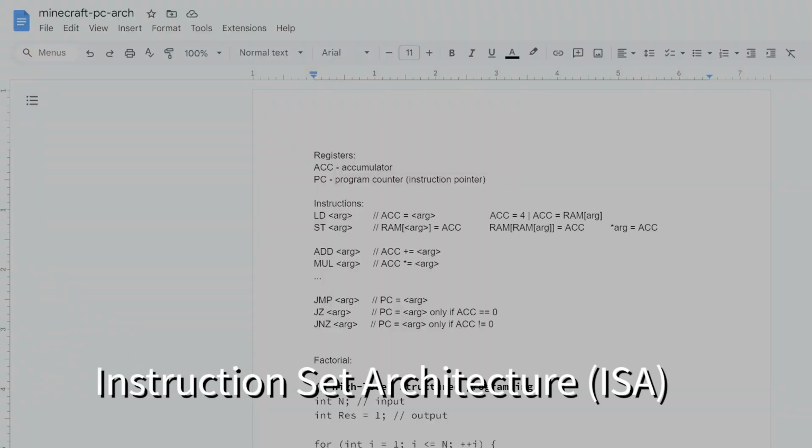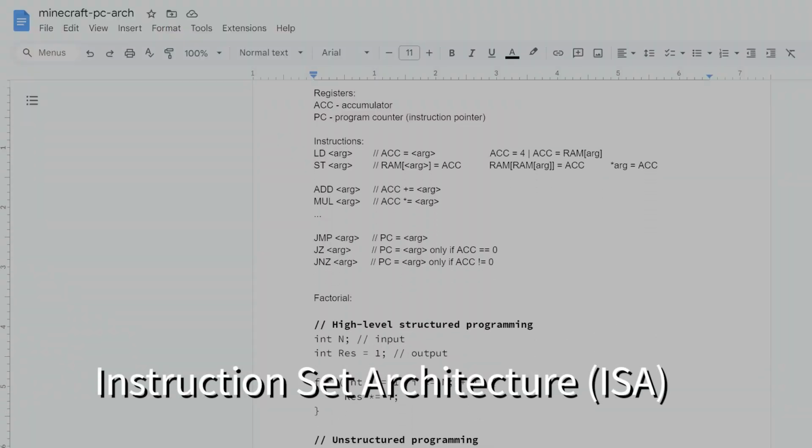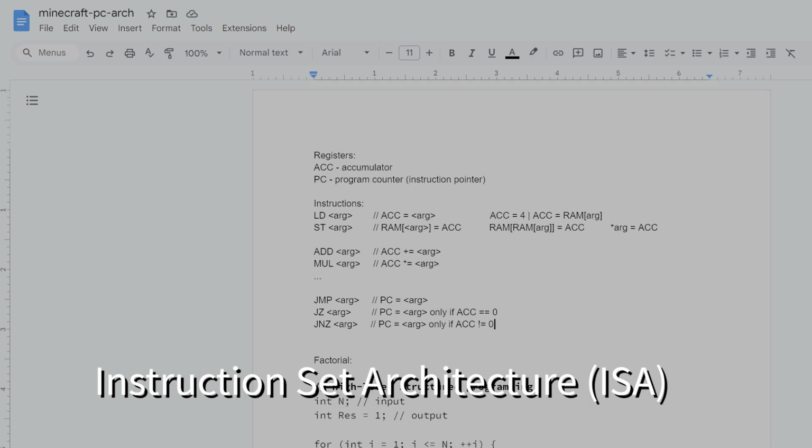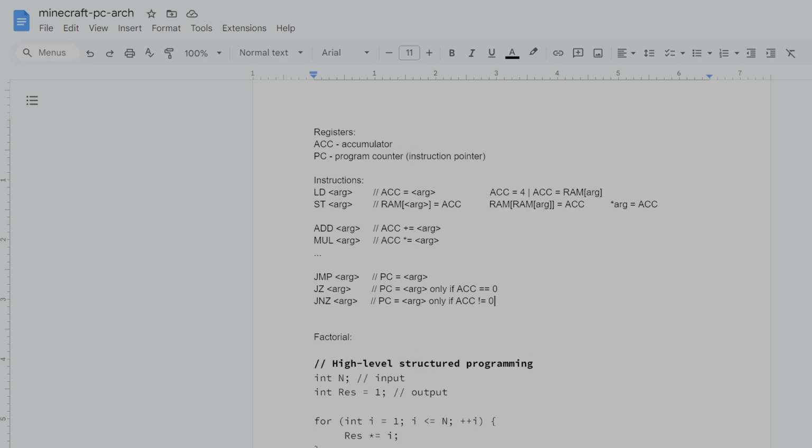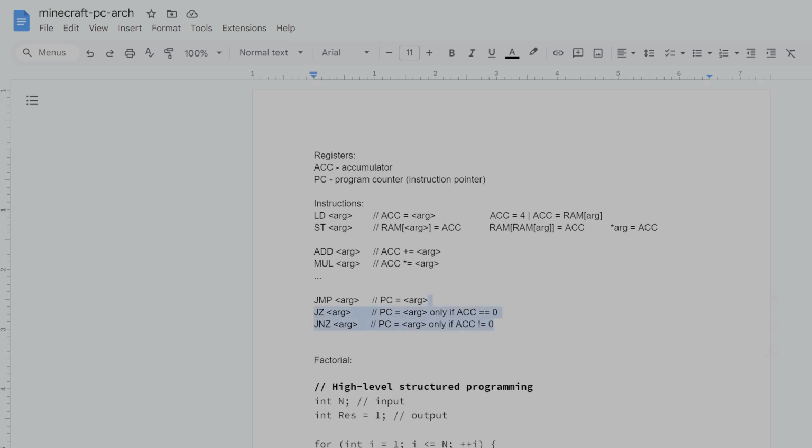All right, so here I'm going to describe some of the instruction set of this computer, which I designed myself, but it's a very simple sort of RISC style architecture. Here I documented some of the semantics of the instructions, although I'm not sure if this is exactly what I ended up with. This is sort of my prototype. But as I described, each instruction is 2 bytes. So you have your opcode and then you have your argument byte to be able to use for whatever.